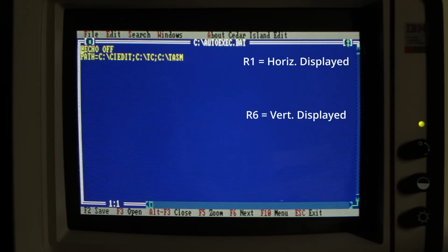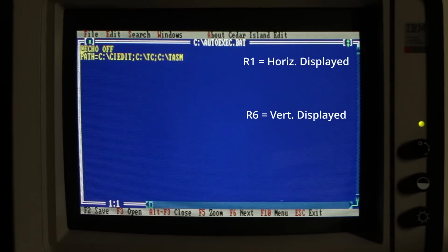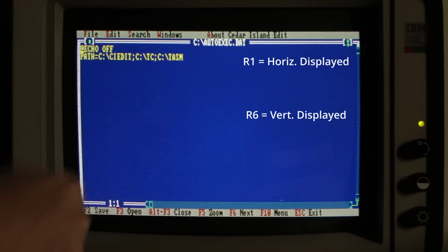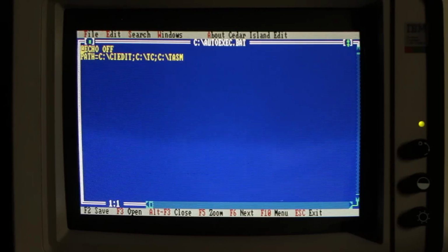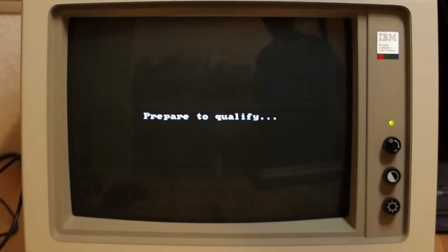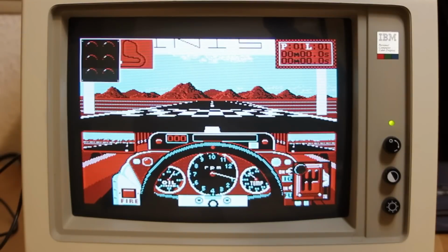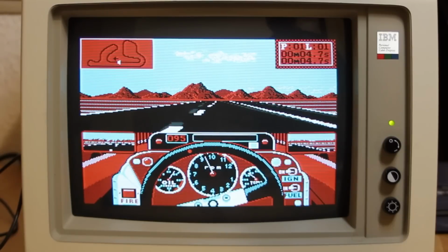And actually the CGA card can run it at two different speeds. One's fast enough to get 80 characters across and the other one only 40. And in both cases you'll get 25 characters down the screen. So those are the parameters that we normally put in those registers for CGA text modes. But we know that the CGA card can also do graphics. The CRT controller chip has no idea about graphics, so somehow the CGA card uses this character device to also display graphics modes, and I'll explain how that works in a moment.